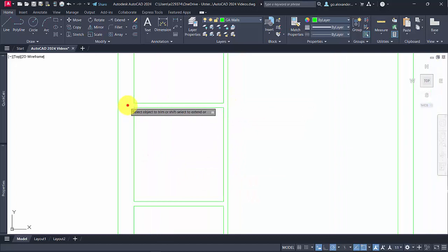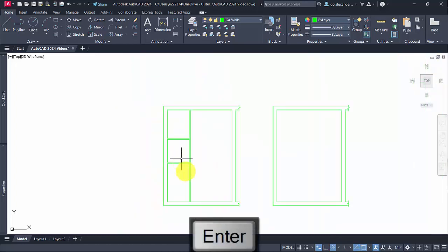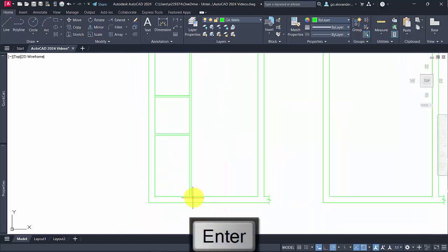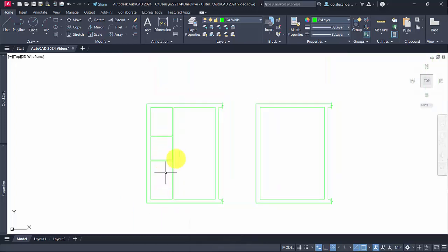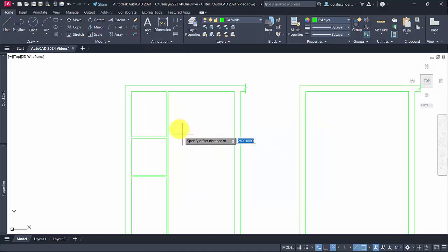If it was a stud wall, you would want to retain the line there. So for example, if it was concrete blockwork for the inner leaf of the cavity and then timber or metal studs inside, you would retain the line there just to show the different materials.